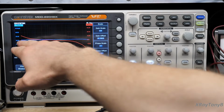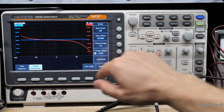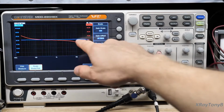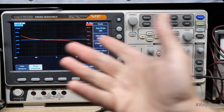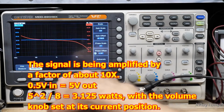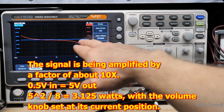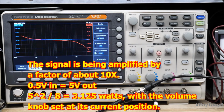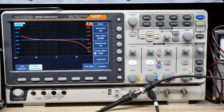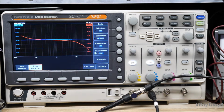And if we look at the input from 20 hertz to 40 kilohertz, look how flat that is. In the gain offset, you're seeing about 20 dB of gain from the input. And notice how flat that is. So this is a very flat amplifier, which is good. That means that the components in the amplifier are still good. We don't have to recap it or do anything like that.